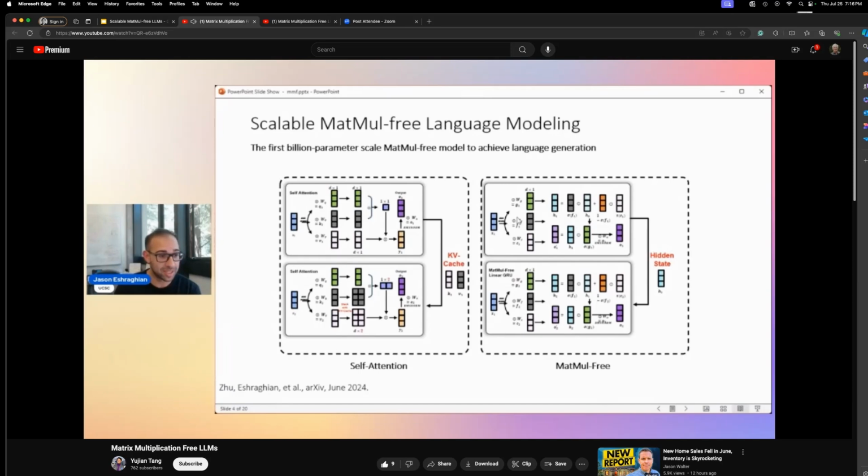And as a result of being ternarized, any linear layer or any linear dense operation is just, like I said, converted into a signed accumulation. So replacing vector matrix multiplication with signed accumulation. From a software standpoint, if you were to code this up in Python, it might feel like there is no difference. From a hardware viewpoint, you can get rid of all of your multipliers. So again, you probably want custom hardware to be able to exploit something like this.